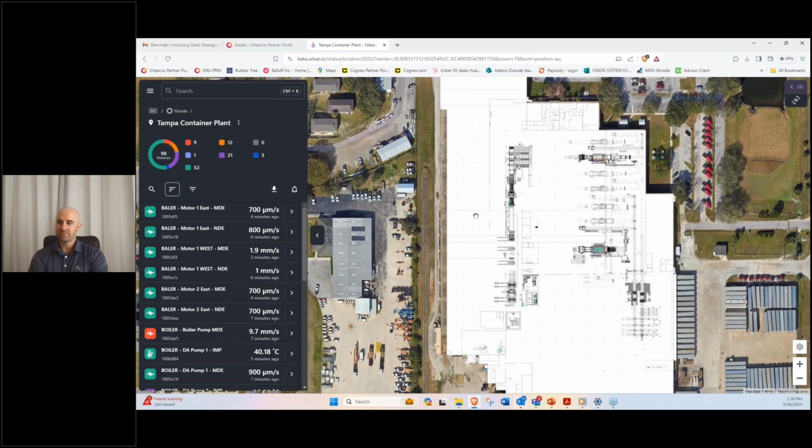And then, Nick, if I remember correctly, on one of the first couple of installs that we did, you were actively monitoring connectivity from the gateway to all of the sensors. In the event that there might be connectivity issues with some of the fringe assets, you could always go back and install another gateway. Is that correct? Yep, that's why we have an extra one. We set up the gateway at the main point that we think is best, and then we range test. So we go to all these different assets. Typically, I'm going to find the furthest away sensor from that gateway with the most obstruction.